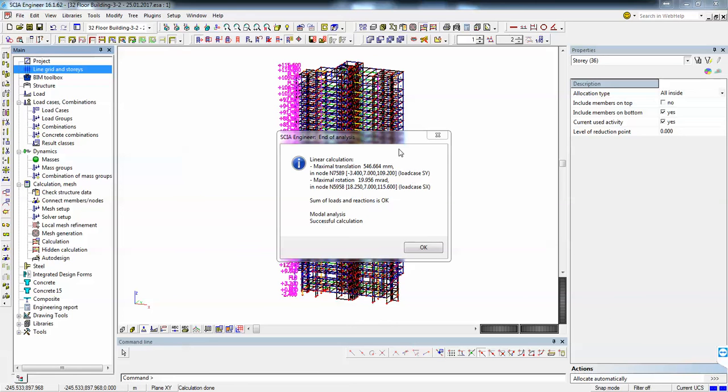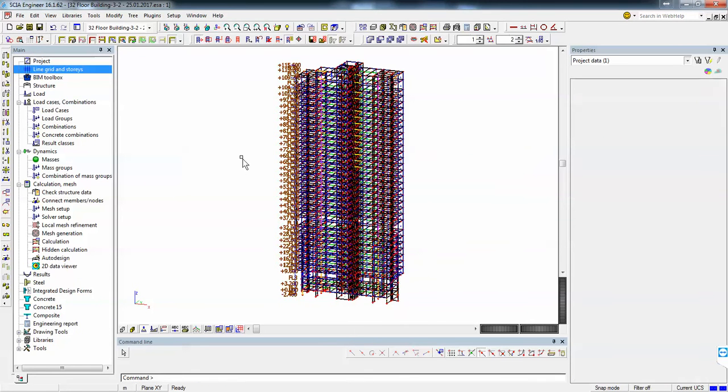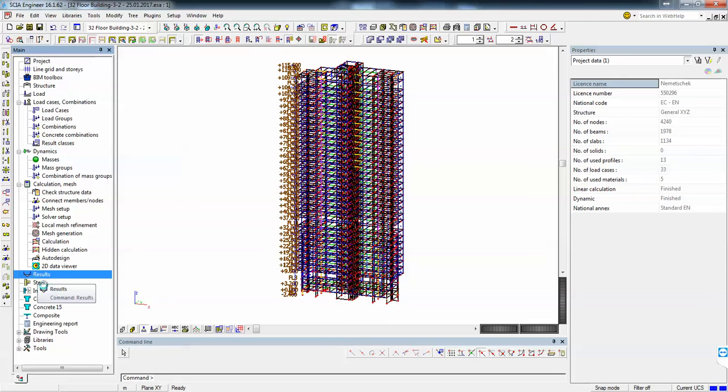The seismic force, we already see doubled deflection on these load cases, but it doesn't really matter. So we only want to evaluate how the building moves and what are the values of displacement only from the wind load combination, not seismic. Okay, seems to save some results. So we'll go now to results.